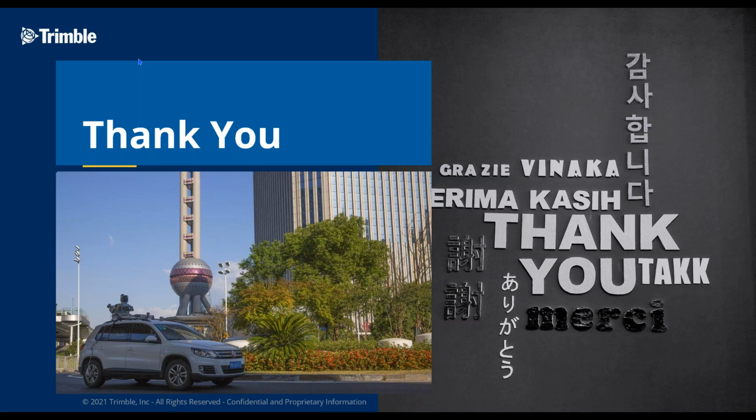Yeah. Is there a plan to be able to process MX2 data in TMX and TBC? MX2 data cannot be processed in Trimble Business Center today, but it's possible to bring MX2 data in Trimble MX software. You just need to keep in mind that automatic tools might not work really well with MX2 data due to the density and accuracy of the point cloud. But you can obviously perform the manual feature extraction. You also could connect to the database and publish data in Trimble MX from MX2 system today.